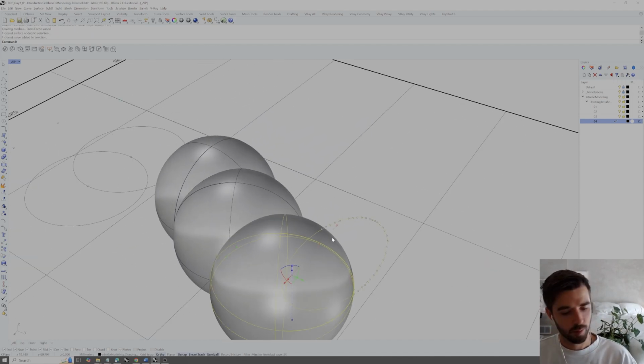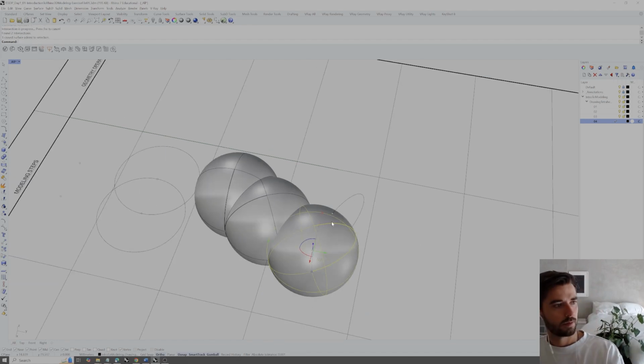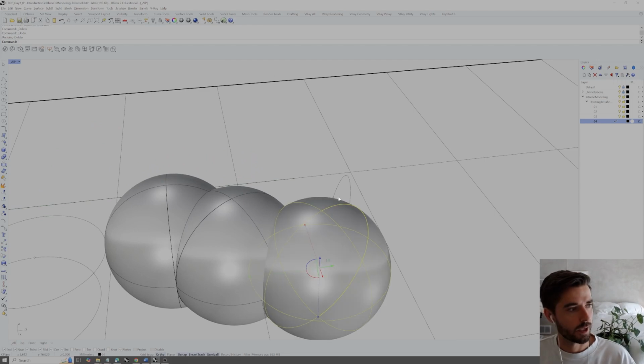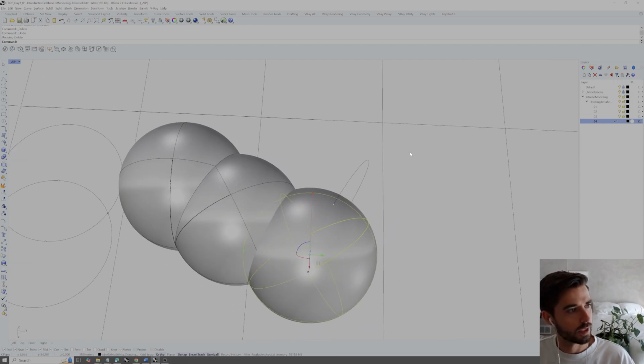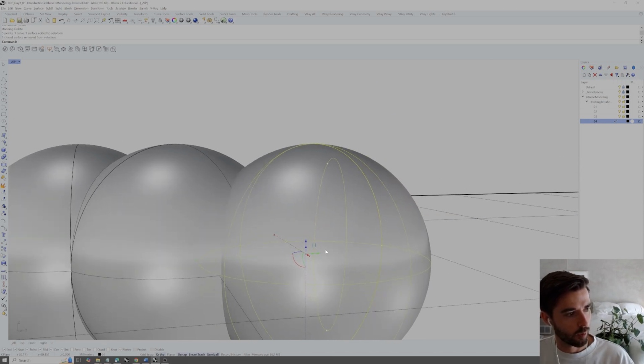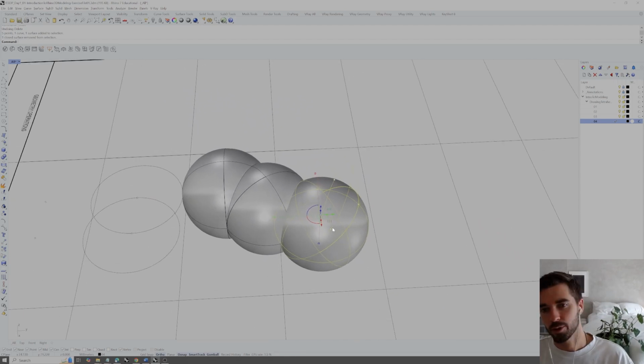Now if I select both of these objects and then type intersect, we can see here that we've deposited this point. So what I'm going to go ahead and do is select everything inside of there, I'm hitting Control, left clicking on that other sphere which we've grabbed just to deselect it, and you can see inside here that we have our base 3 points, we have that point of intersection, our circle, sphere, and then that other point of intersection.